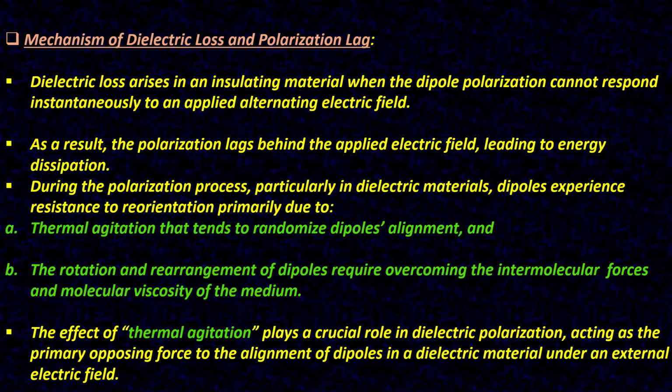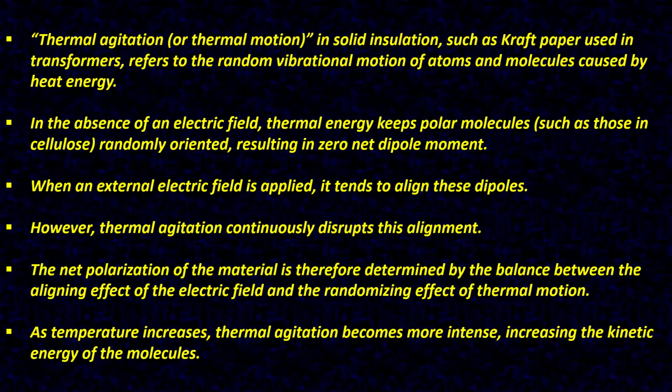That is, thermal agitation, most important. Thermal agitation or thermal motion in solid insulation such as paper used in transformers refers to the random vibrational motion of atoms and molecules caused by heat energy.